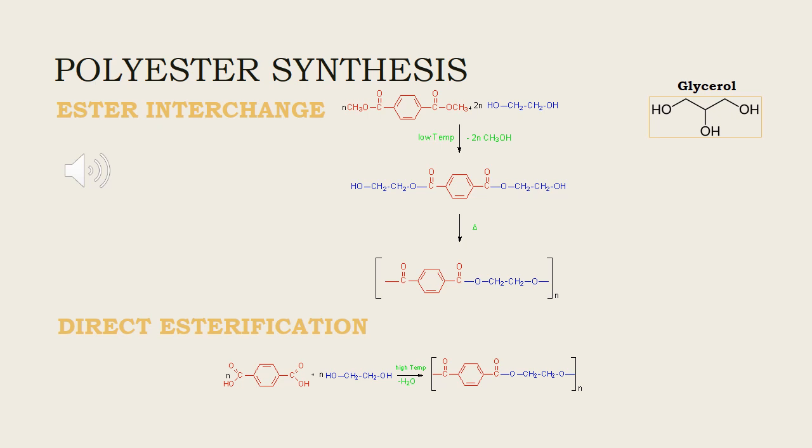Such a molecule can grow to very high molecular weight if internal coupling occurs. Internal coupling is the reaction of a hydroxyl group and an acid functionality from branches of the same or different molecules. In that case, the polymer will become cross-linked. Rigidly cross-linked polymers are totally unaffected by solvents.